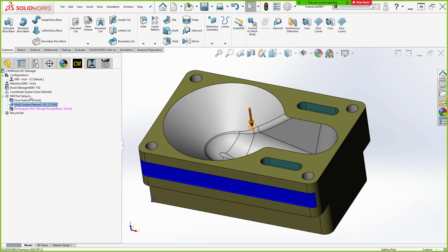You can re-identify fixtures in a different way, re-identify your parts in a different way. CAM will allow you to put all your different fixturing, all your different setups, into one file. And then CAM configurations will allow you to treat it as piecemeal, right? Like, okay, in this setup, I'm only going to use these two things for fixtures, and in this configuration, I'm going to use these two things for fixtures. So a CAM configuration here would basically just reset yourself. When I do that, I get a blank feature tree. But it's better to contain it in one part file, obviously. Managing multiple part files is painful.